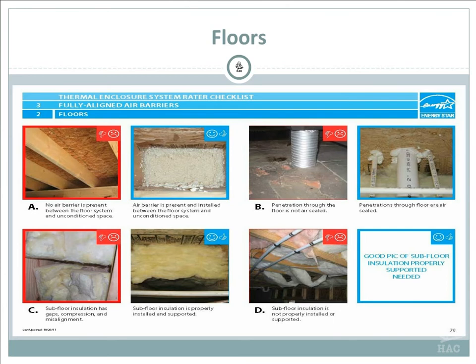The problem with just putting an R11 or an R13 in there is that insulation is going to drop down to whatever's holding it up, chicken wire, tiger teeth, whatever, and it's going to create a void between the insulation and the floor, and that's going to keep that floor cold. So you're doing all that for naught. It has to be a full 6-inch insulation batt in there, held in place. Again, perimeter insulation, it might work. You'd have to check with your rater.